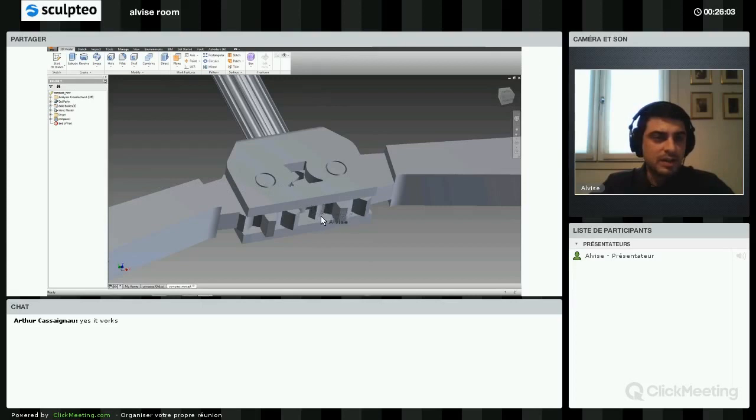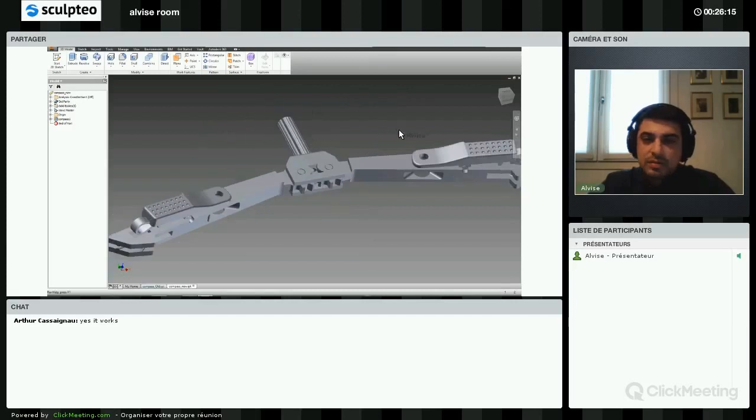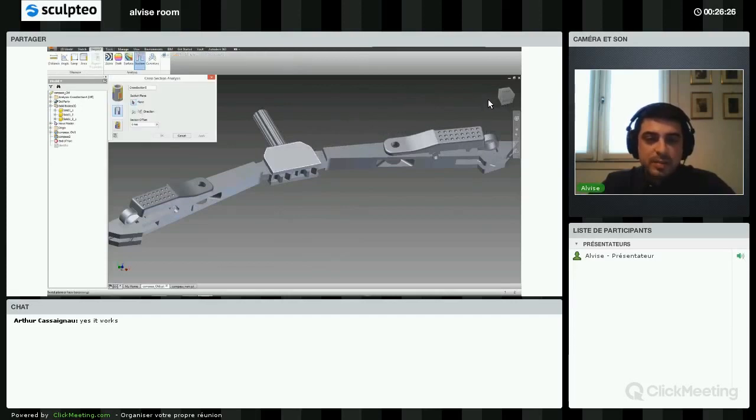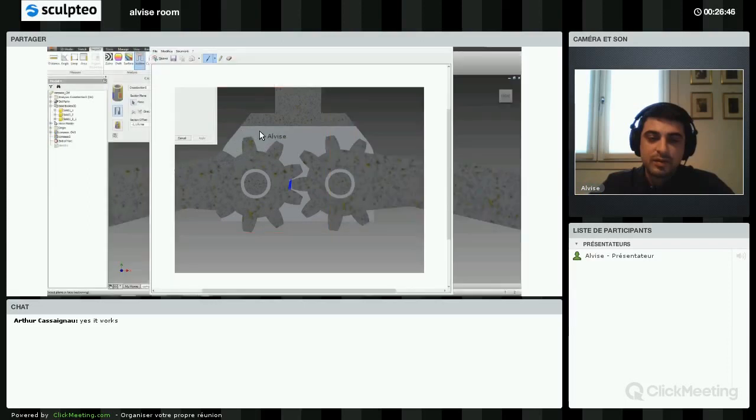I'm taking the inspect tool and section. Let me show you first the horizontal section here. From this section, you can see that what I define as a straight escape path for powder is not present here in the middle. The powder at the center is very likely to get stuck in this part, as the escaping path is quite complicated and difficult. And of course, I'm using the minimum clearance possible to make the whole object more precise, so that it can be used as a proper design tool.